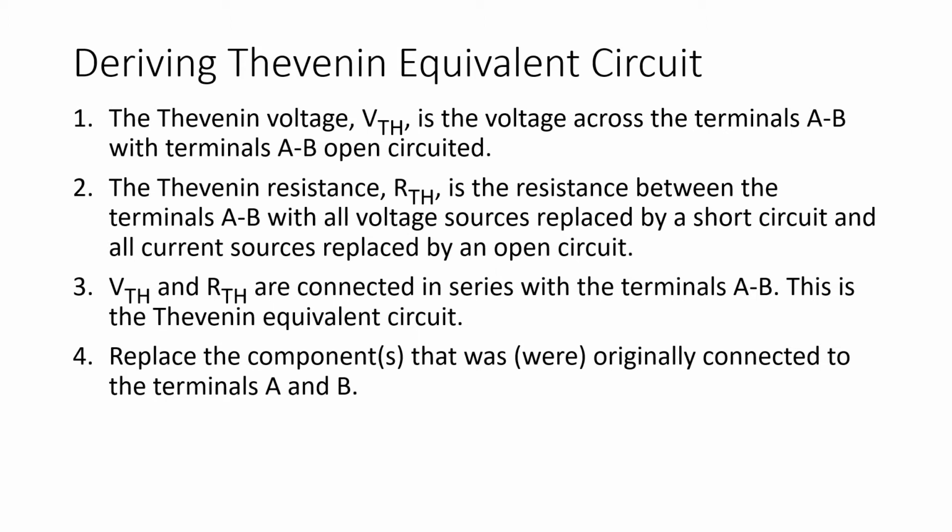Step 3, we connect the Thevenin voltage and the Thevenin resistance in series with the terminals A and B. This is the Thevenin equivalent circuit as we saw in Figure 1. Then we replace the component or components that were originally connected to the terminals A and B.